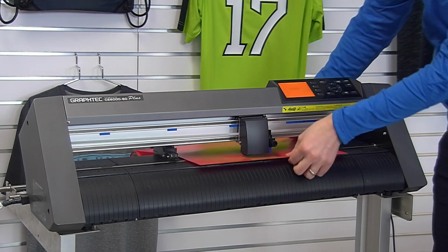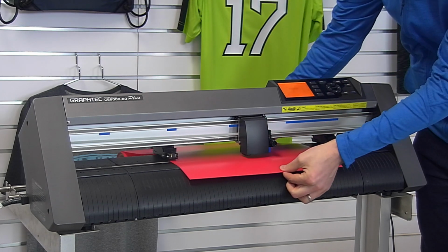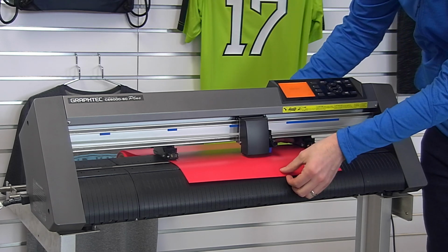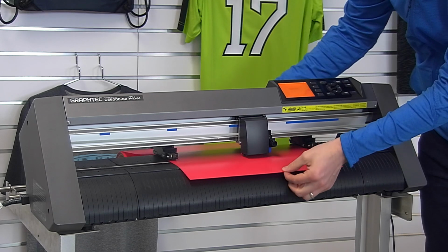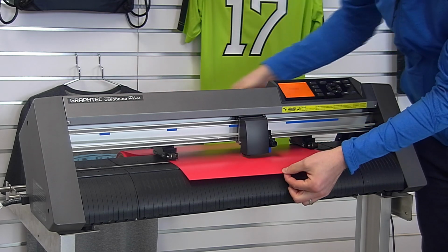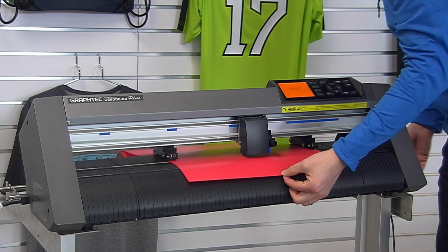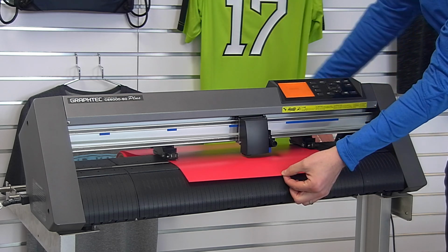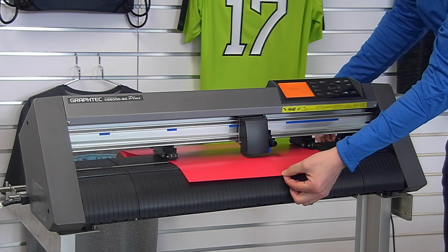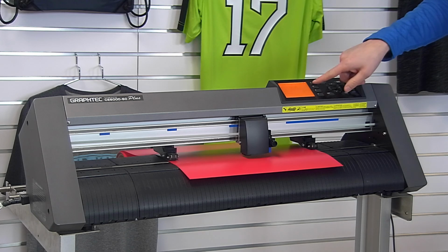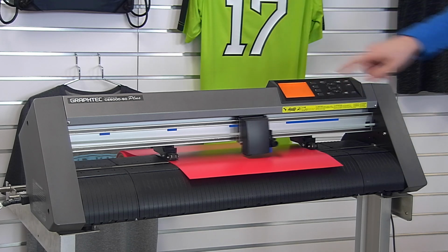I'm just loading the material onto the stand, and then I'm going to make sure that I have my pinch rollers into place on the edge of the material. I don't like to squeeze the boundaries too much. I pull my material tightly to the edge, and then I'm going to lock down my hold down device, which is right on the back of the machine here. And tell the machine I want you to find the front edge of that material.